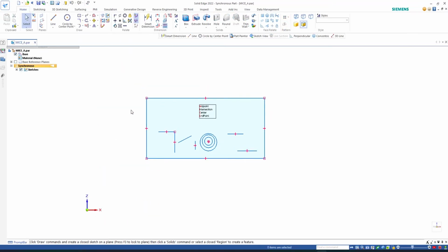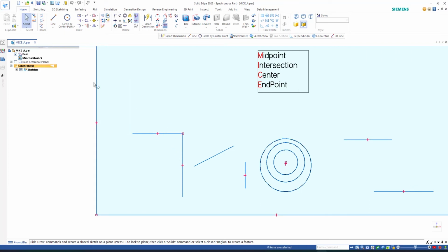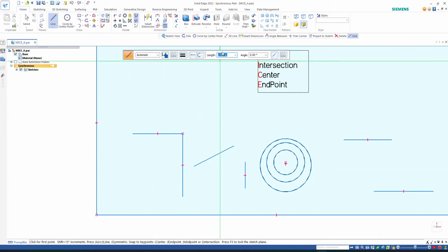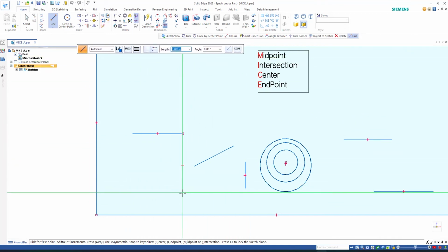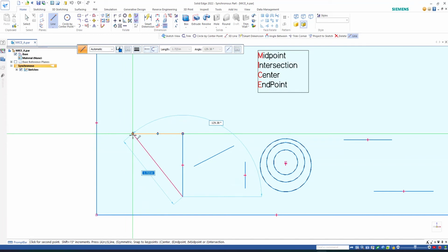Okay, little tips here. When you find yourself in the sketch, and you want to use, for example, a line, and I want to use a midpoint of this, say I snap into that. Obviously, you can always do this, right? Snap right in here, left click, and you can always go to the endpoint or midpoint as indicated there.